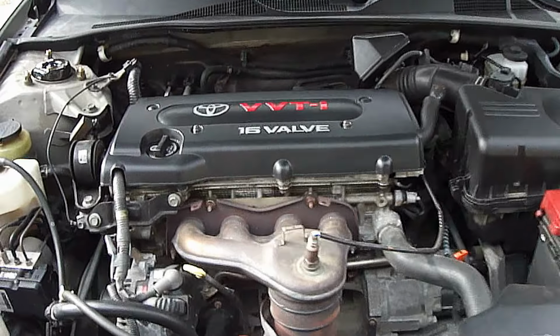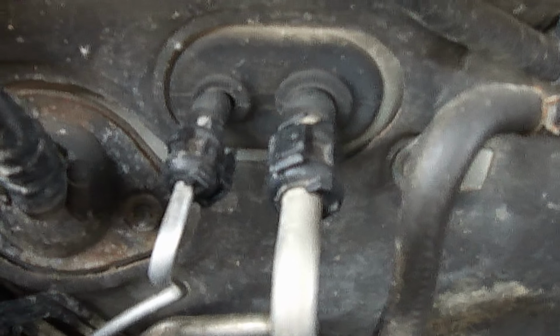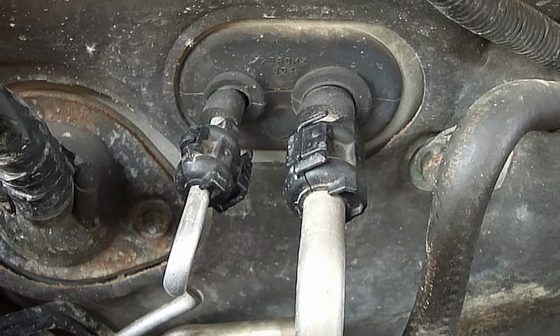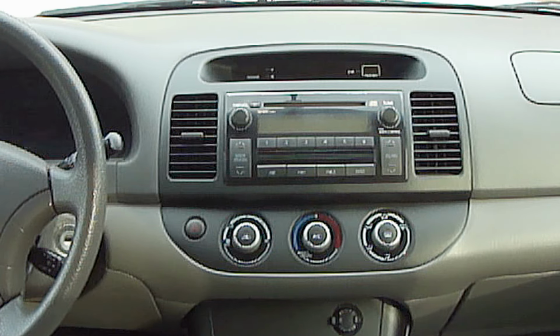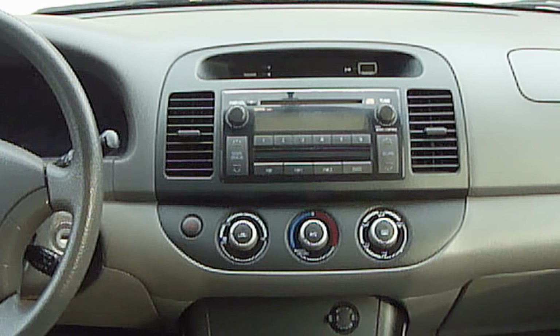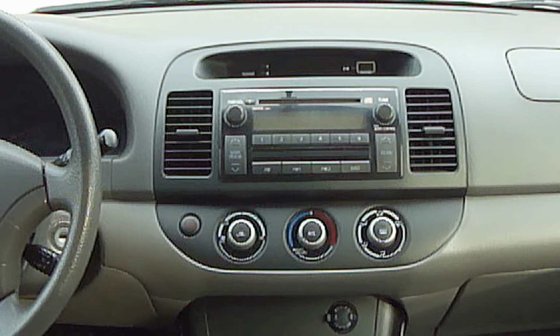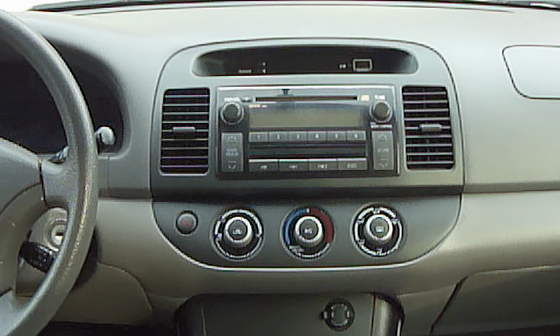The low side pressure switch on this vehicle is located past the firewall here by the AC lines inside the dashboard. Removing the dashboard can require hours of labor, so before removing the dashboard, it would be wise to first have a repair shop check the low pressure switch with an advanced diagnostic scanner to confirm that the switch is bad.